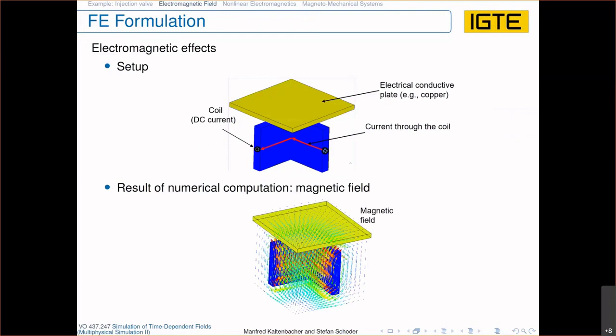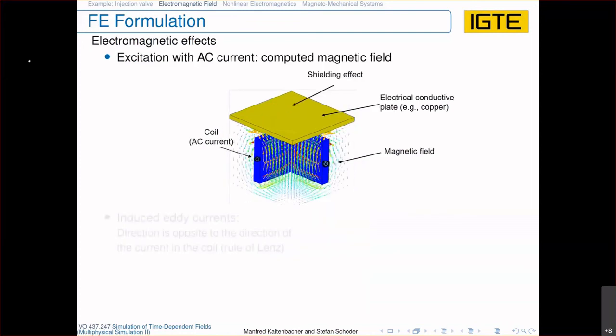However, you have to be careful, it is the steady state case. So if you immediately switch on and you do a time step, a transient analysis, then it is clearly a switching on of the current, and you would have some transient effects. But when you do clearly a static analysis, because the coil current is a DC current, then clearly you will get this result.